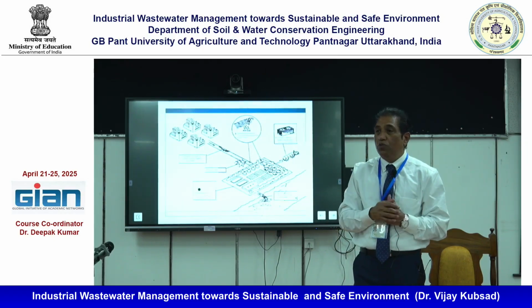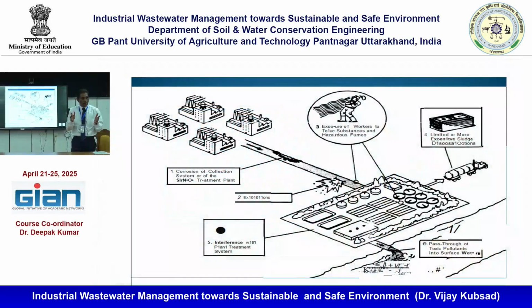That low pH wastewater will react with the iron reinforcement in the sewer system and destroy it, right? If the wastewater is gasified, if it consists of a lot of methane and is not properly maintained, there is a possibility that it may cause an explosion, right?